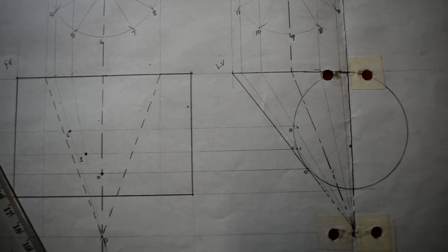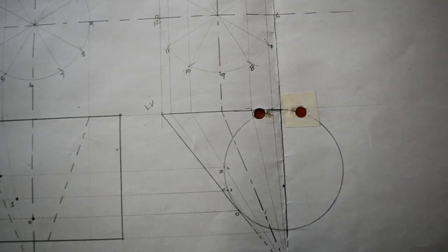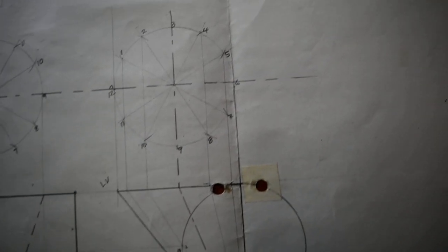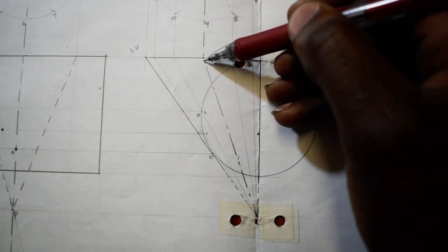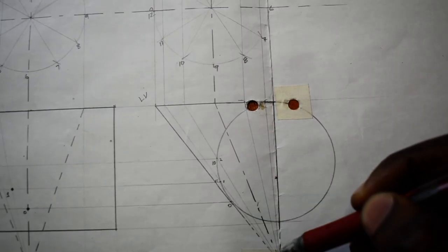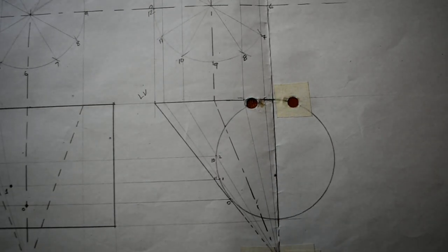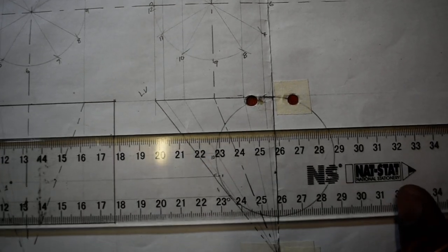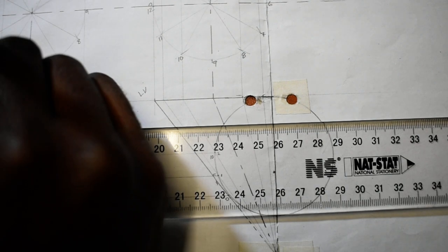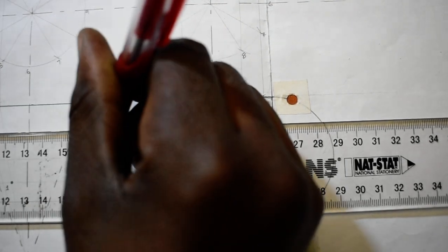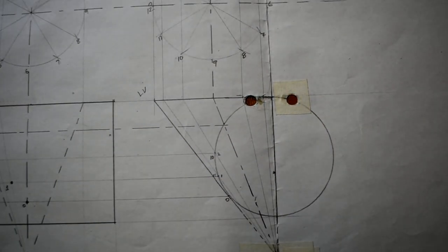So now let's get point 3, and point 3 is the center. Actually everything starts from the auxiliary of our left view. You understand? So point 3, which is the center. There it goes. Once it touched there, it was directed to what? To your apex point, isn't it? Once it touched the main pipe, you take it horizontally, and I will draw it as a center line. How do you draw a center line? Short, long, short, long, short, long, short, long, short, long. You understand? So there it is.